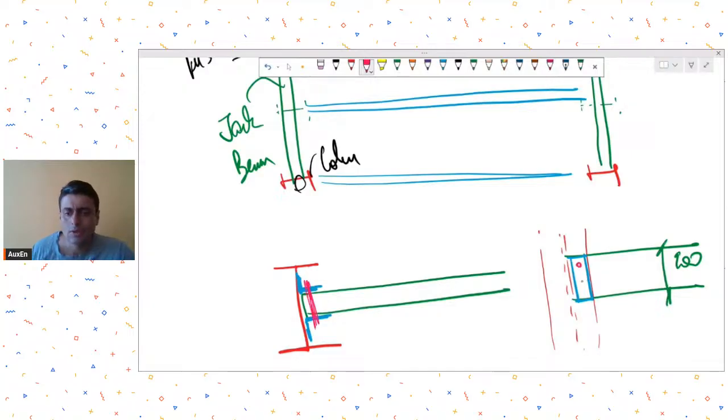So in my opinion this will be the simplest way in which you can provide this type of shear connection on site, for RHS to web of I section connection. So provide these web cleats and then get it connected.